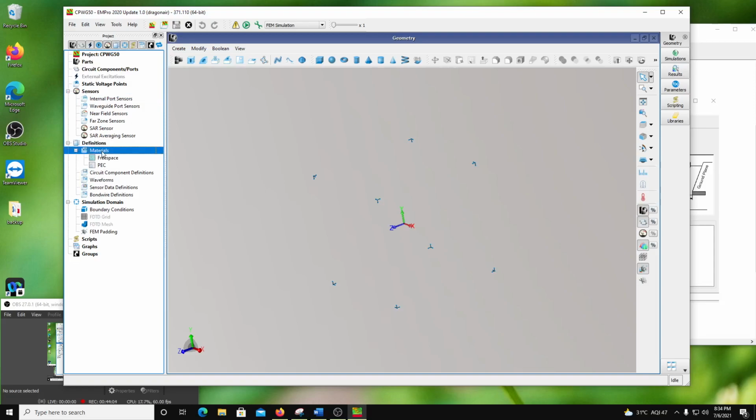So you have got materials. So in this case, okay, perfect electric conductor, that's the bottommost. It can be a metal also, it can be a sheet, which is perfect electric. Okay, now free space is everything is free space. Once you draw, then the free space is taken away by whatever you draw. Okay, so that's what the material is. You can right click and you can add new definition of a material. So it shows up as a new material.